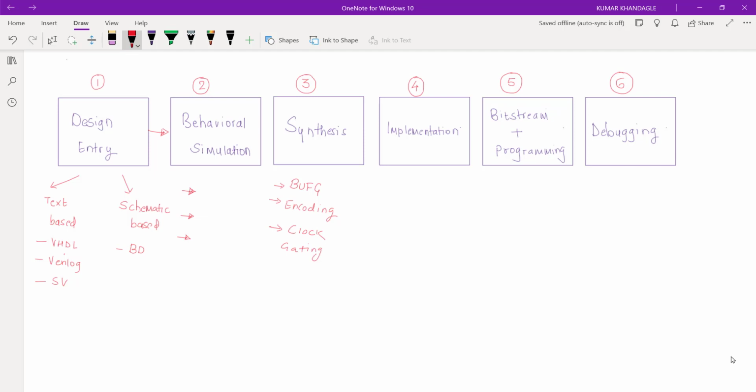Now you could see that when we specify our HDL, it will be transformed to FPGA primitives. So it becomes mandatory to verify whether our system still behaves as expected, because when we perform a behavioral simulation prior to synthesis, we consider an HDL code. Now the HDL code is transformed into primitives, so even if you do not apply the synthesis strategies, it becomes mandatory that you perform a behavioral simulation.